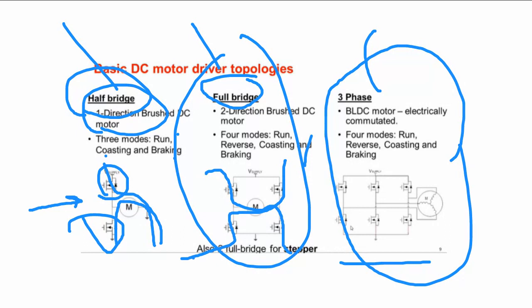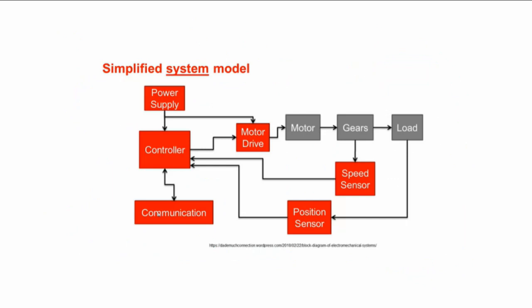So all of this is very generic in terms of all these systems, but beyond the motor drive, as far as electronics, we will also need a microcontroller of some kind. Typically that will make the decision based on, well, what's my desired motion? What is my speed right now? What position have I achieved?